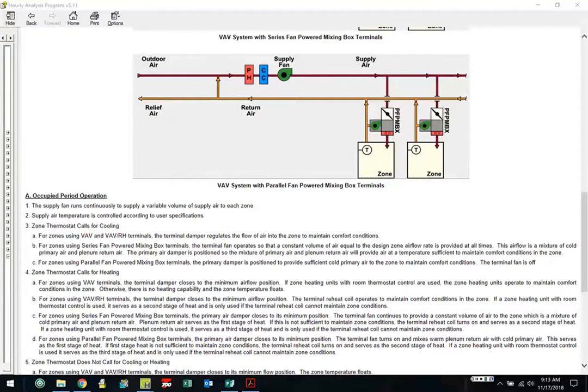Conversely, in the summertime, we're trying to cool this down to 55 degrees. So in the summer, we'll be at minimum outside air, the smallest amount we can bring in. Typically, there's an airflow station on there that actually measures airflow, and we document how much air is coming into the building. And then we cool that down to 55, 57 degrees. So theoretically, when we look at this system, it's variable volume, but the temperature pretty much stays the same. With that VVT system we talked about earlier, essentially this unit is changing over into heating mode or cooling mode, and it keeps doing that. With a VAV, we're designed to maintain cool temperature coming into it.